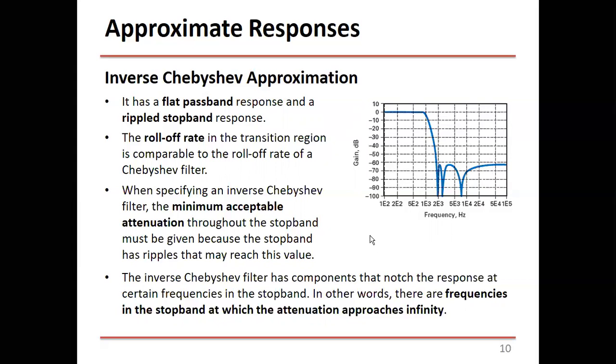In the inverse Chebyshev, you will find certain points where you have deep notches like this in the stop band. It does not matter too much because you're already attenuating. You are already attenuating everything in the stop band by at least how much here? At least minus 60 dB, right? So the attenuation here is minus 60 dB, and minus 60 dB is a really huge number. If you'd like to know how much this is, take the inverse. Some frequencies have even deeper attenuation than 60 dB.